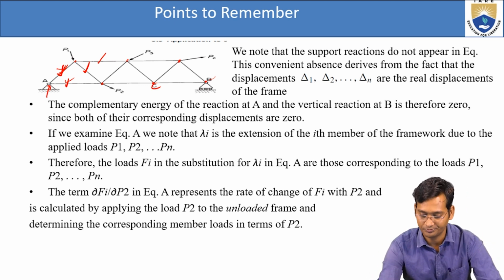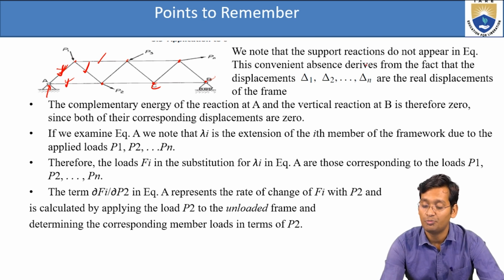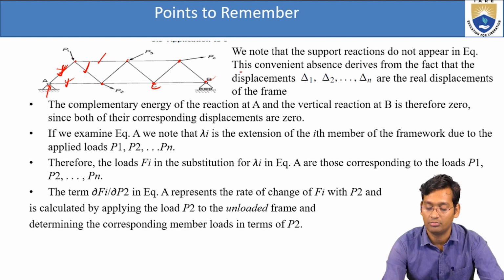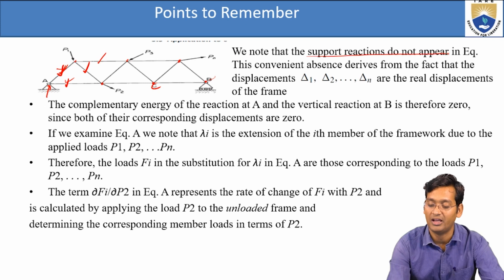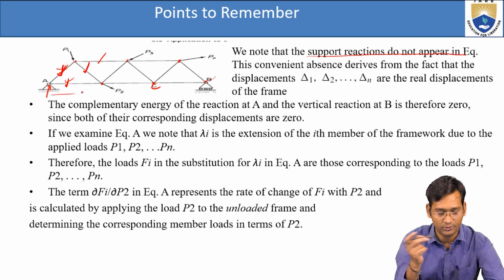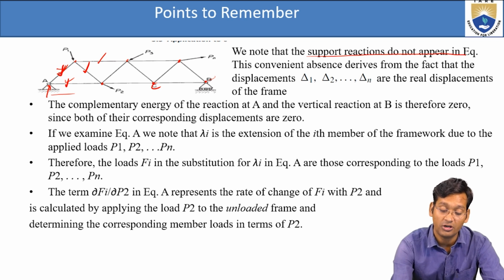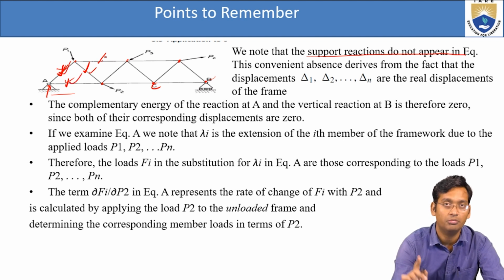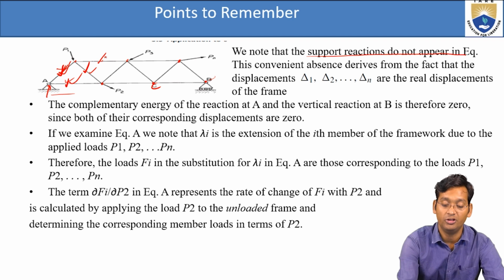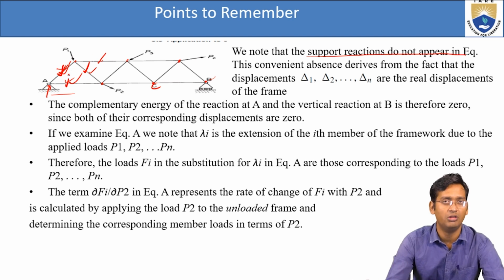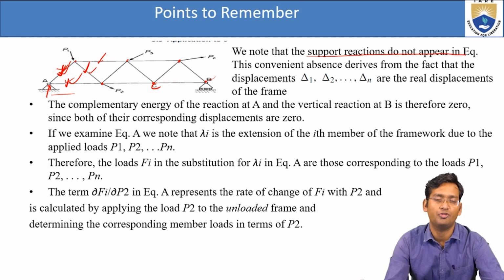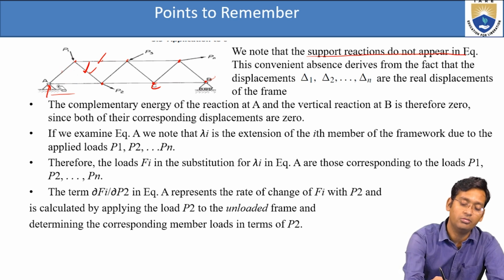Just see here, we know that the support reactions do not appear in the equation, right? So support reactions do not appear in this one, right? But we have to find the support reactions to find what? Forces in each member. Depending upon how much load is acting, based on that we will find the support reactions, and based on the support reactions only we will find the load in each member.